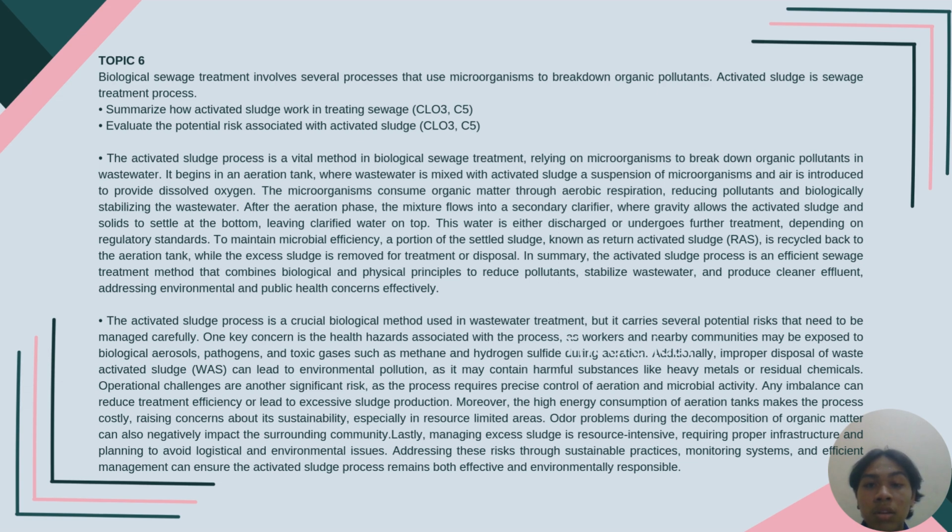The activated sludge process is a crucial biological method used in wastewater treatment, but it carries several potential risks that need to be managed carefully. One key concern is the health hazard associated with the process. Workers and nearby communities may be exposed to biological aerosols, pathogens, and toxic gases such as methane and hydrogen sulfide during aeration. Improper disposal of waste activated sludge (WAS) can lead to environmental pollution as it may contain harmful substances like heavy metals or residual chemicals.